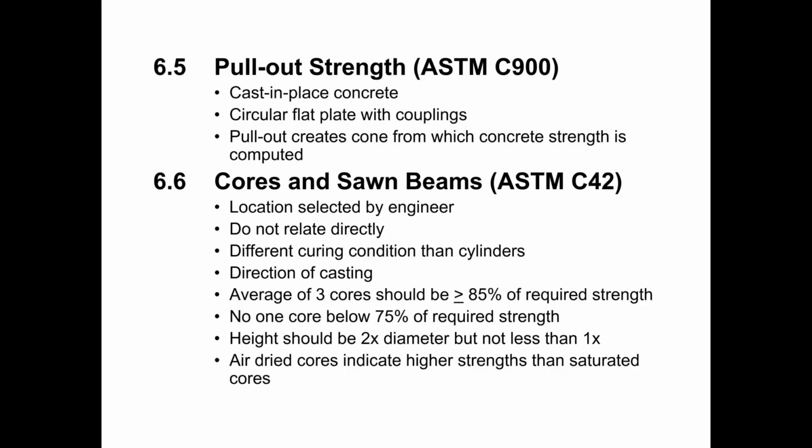Now keep in mind, that's an ASTM C42 requirement. If a plant is doing work for a DOT or some other government agency, that government agency may have their own specification with regard to cores. Their specification may require that the core achieve 100% of the required strength.